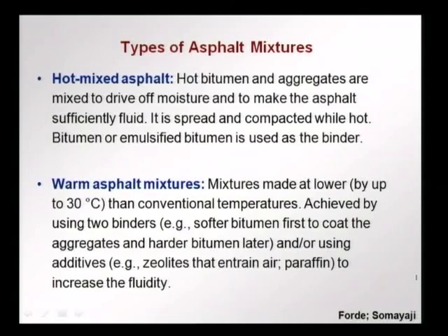Also, very often additives are used to increase the fluidity of the warm asphalt mixture. Examples of the additives used are zeolites that entrain air and paraffin, which facilitates the fluidity. So, here as I mentioned earlier, we have warm asphalt mixtures which are similar to hot mixed asphalt, but can be worked at lower temperatures.